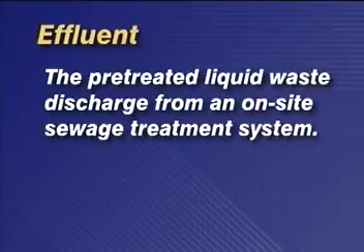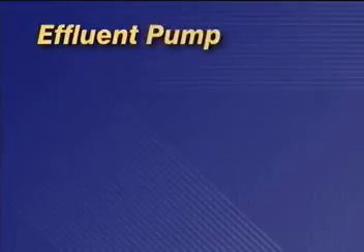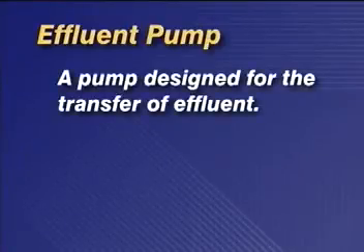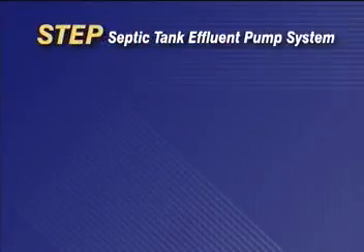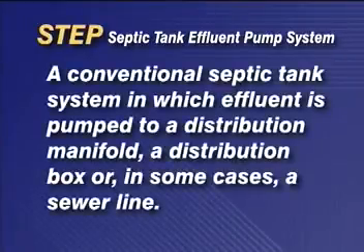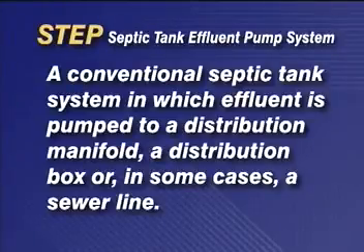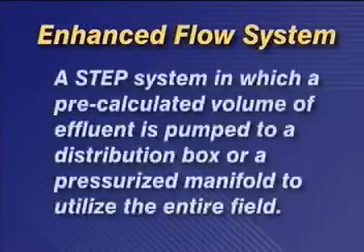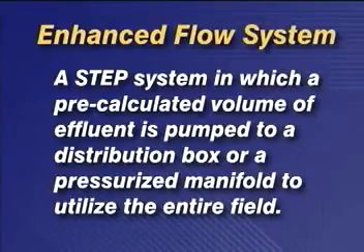Effluent is the pre-treated liquid waste discharge from an on-site sewage treatment system. Effluent pump is a pump designed for transfer of effluent. STEP, septic tank effluent pump system, is a conventional septic tank system in which effluent is pumped to a distribution manifold or a distribution box for conventional distribution, or in some cases, a sewer line. Enhanced flow system, a step system in which a pre-calculated volume of effluent is pumped to a distribution box or pressurized manifold to utilize the entire conventional distribution field.